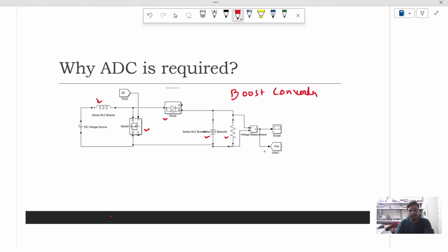Okay, here you can see the sensed voltage in simulation. The output voltage is V0. Now what we do here, I have a comparator suppose. The input voltage is coming, which is sensed from the output, and this is a reference. Suppose I take it Vref. This is the reference, maybe it depends on how much you want to regulate. So to regulate output voltage, we have to make a control loop.